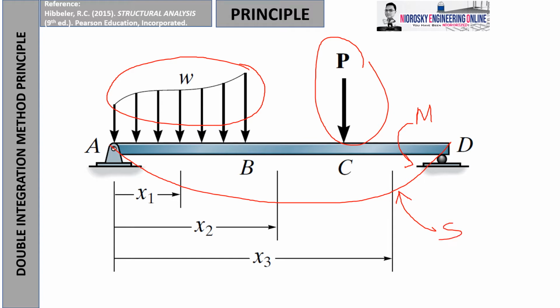So this one, where the beam suffers a red-colored curvature, is what we call single curvature. Okay. Single curvature. And sometimes it can happen like this, double curvature. So it depends on the load nature applied, because the load may change the direction of the deflection and some rotations. Okay? So this is what we call double curvature.